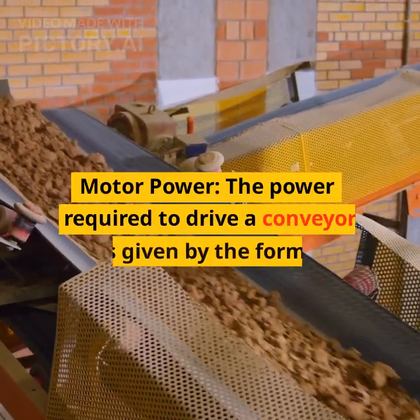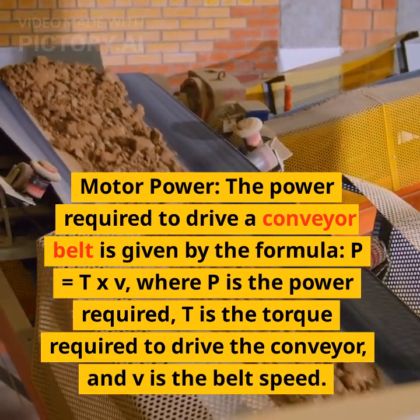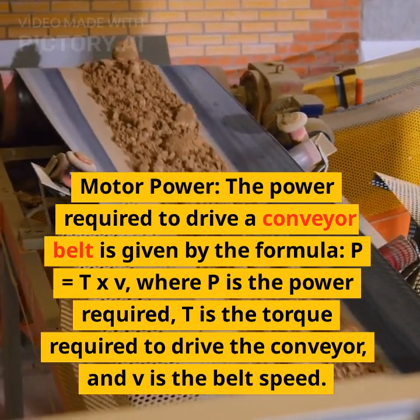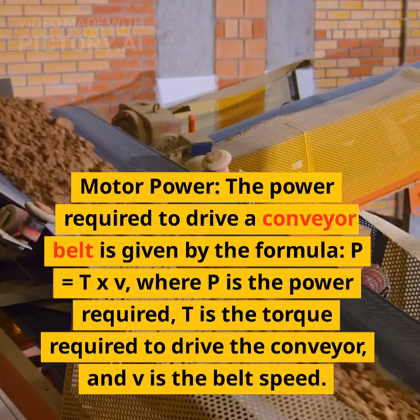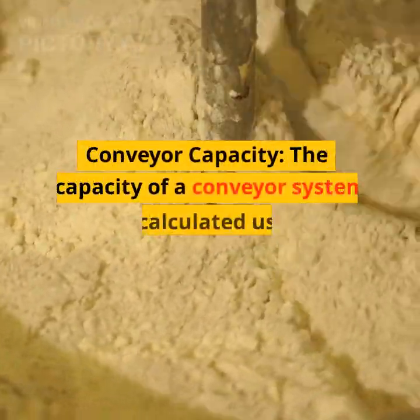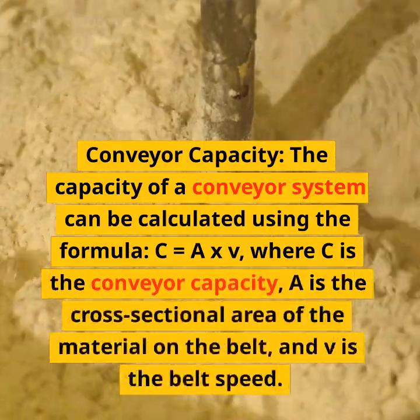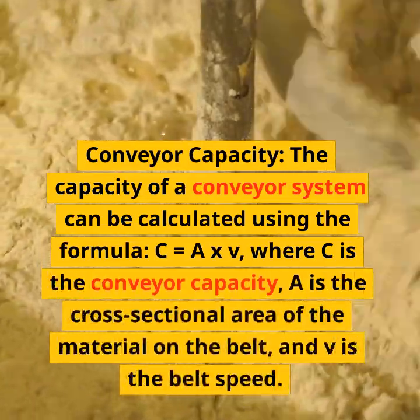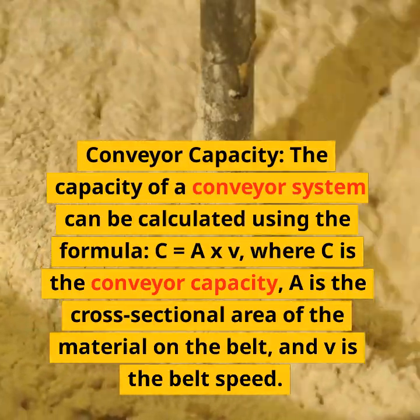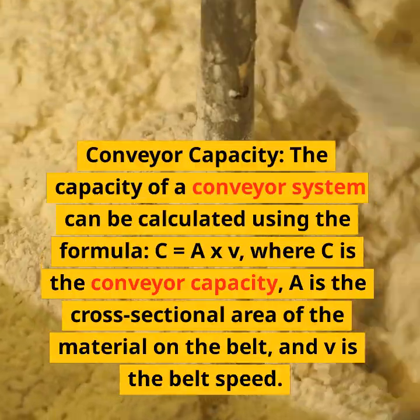Motor power. The power required to drive a conveyor belt is given by the formula P equals T x V, where P is the power required, T is the torque required to drive the conveyor, and V is the belt speed. Conveyor capacity. The capacity of a conveyor system can be calculated using the formula C equals A x V, where C is the conveyor capacity, A is the cross-sectional area of the material on the belt, and V is the belt speed.